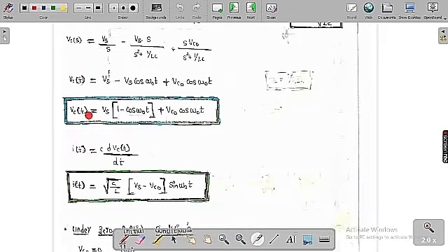it is going to generate the power. So Vc of t is equal to Vs into 1 minus cos omega naught t plus Vc naught cos omega naught t, and I of t is equal to under root of C by L into Vs minus Vc naught sin omega naught t, whereas VL of t is equal to Vs minus Vc naught into cos omega naught t. And omega naught is equal to 1 by under root of LC.